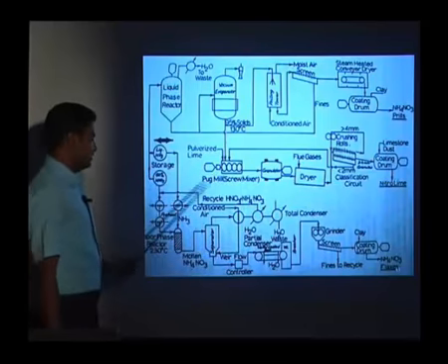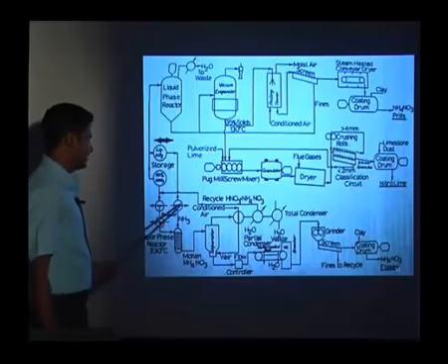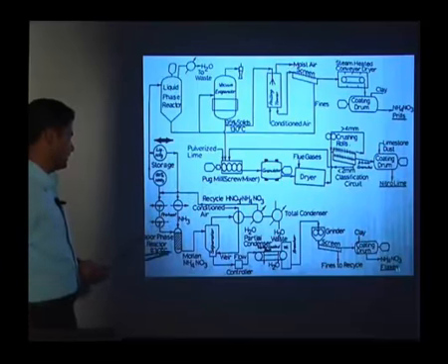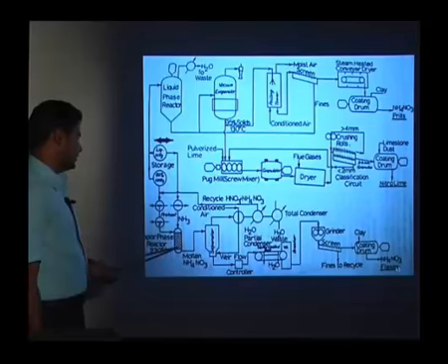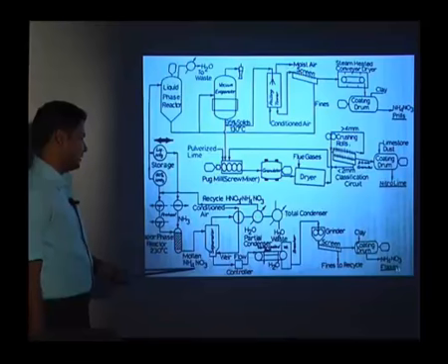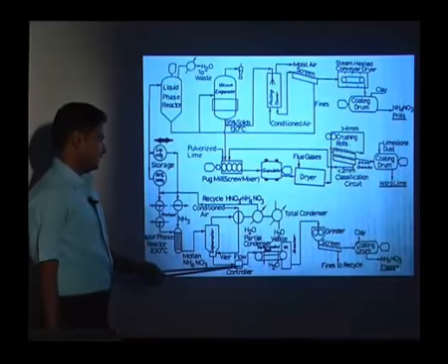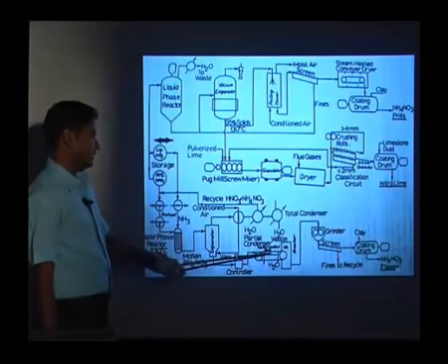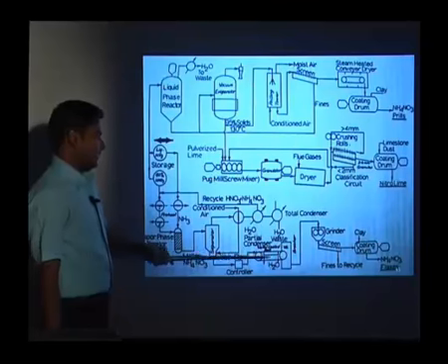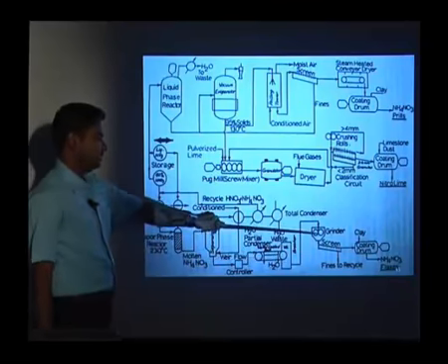When you want the ammonium nitrate flakes, then they are preheated, then sent to the vapor phase reactor at 230 degrees Celsius, and then molten ammonium nitrate is sent to the separator where it separates the gases and the product. Then it is sent to the flow controller and then the condenser. Then the water percentage is removed over here. Then they are sent to the grinder.